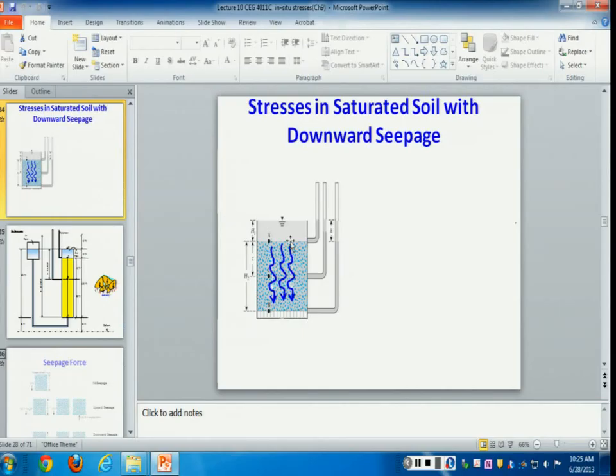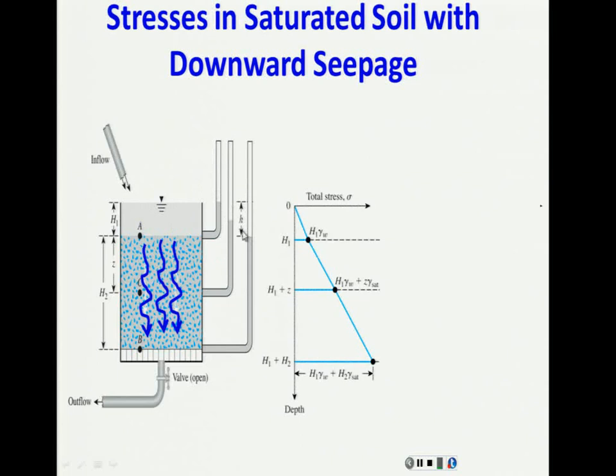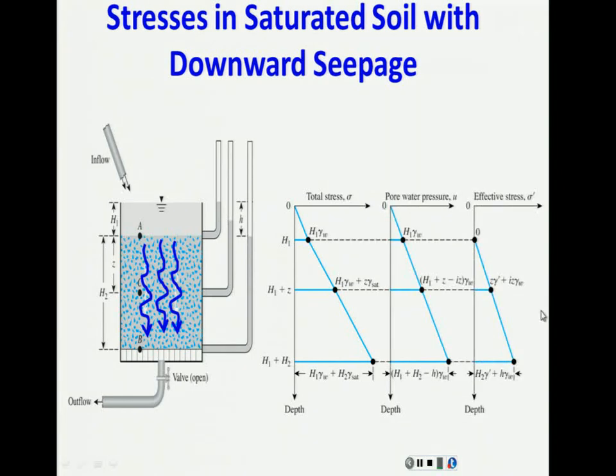I don't know what happened here. You didn't see that. This is what happened there, basically. So when that happened, this is occurring here, and basically what you are doing is that the pore water pressure in this part is decreasing, as you can see, and because of that the seepage is increasing.